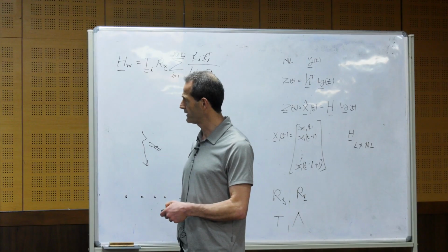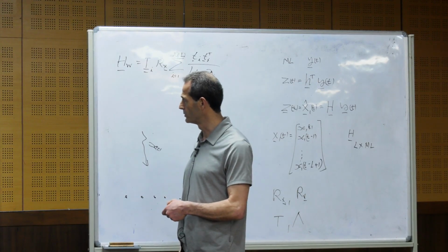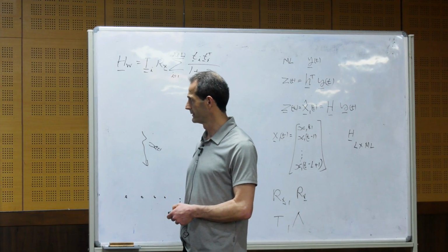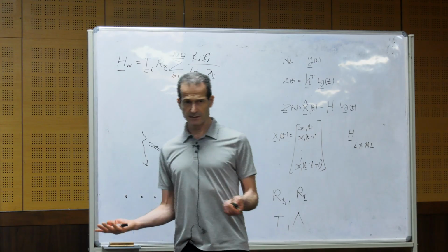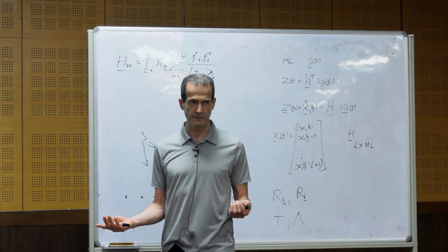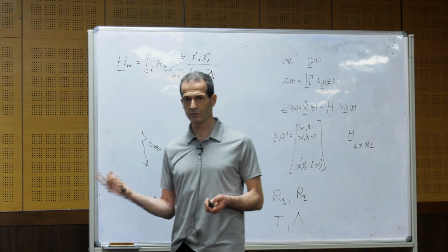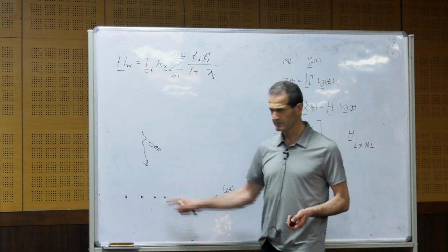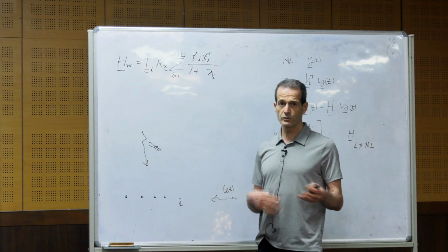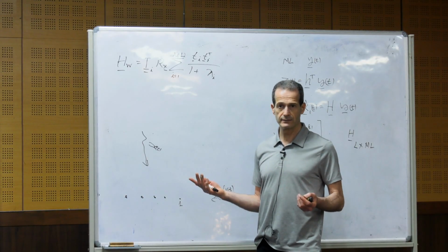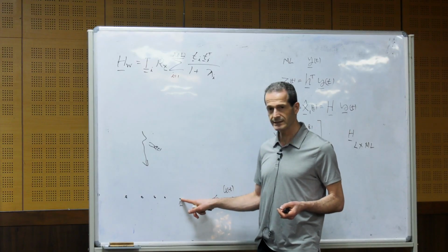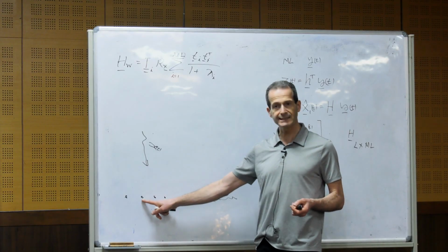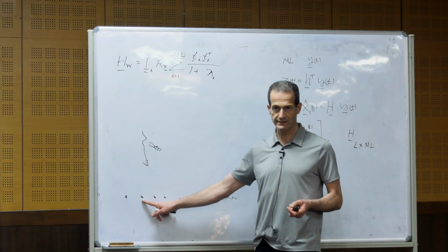And also we can find this matrix, Ru, for the interference. And for the thermal noise, what do you think? What will the correlation matrix be for the thermal noise? It's totally uncorrelated, because any sample from one sensor is uncorrelated with any sample from another sensor.